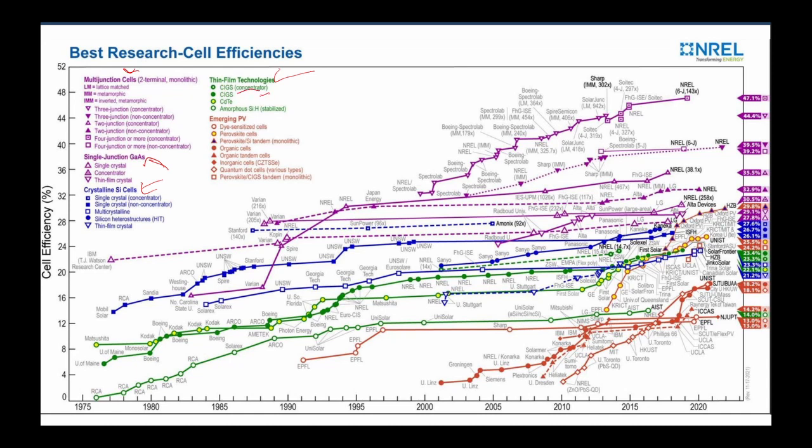There is a difference between concentrated and non-concentrated solar cells. Concentrated solar cells use lenses or mirrors, such as a concave mirror or convex lenses. With a convex lens, we can concentrate the light. If we have a bigger lens, we can concentrate the light falling over it to its focal point. If we put a solar cell at the concentrated spot, it will be more efficient.